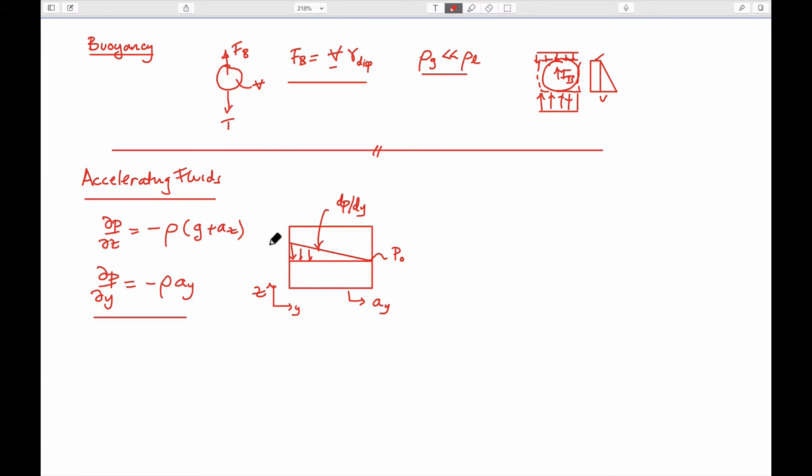And if we just look at an individual triangle that represents this, then this would be distance in the y direction, and this would be how pressure changes. So we know that the isobars in this tank are going to be inclined because it's moving. It's basically bulldozing this at the back. If it's closed, the water has nowhere to go, and therefore this has to be the fluid pressure distribution, which is given by this magnitude here. And so if we want to calculate the fluid pressures as they change, we could take the magnitude of the fluid pressure and just rewrite it as this.